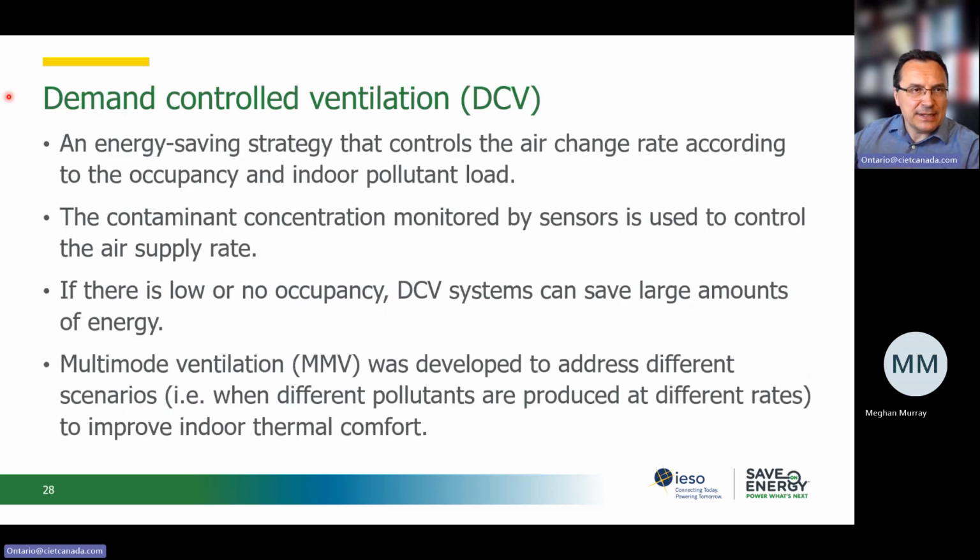Demand control ventilation is a concept applied in our HVAC system design, because most systems will be designed for the worst case scenario, but most of the time we apply a modulating strategy to operate the system at the required capacity for our space.